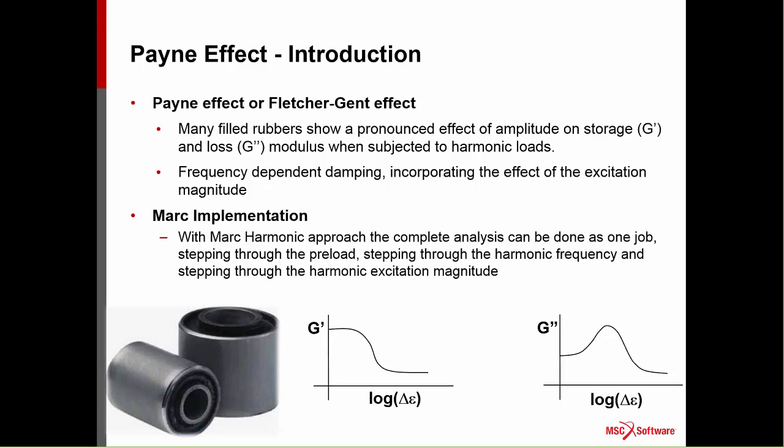So what this really does is it makes that harmonic simulation really a nonlinear harmonic simulation. So we basically apply some preload, we apply an excitation onto that preload. We basically take a look at the amplitude of the results, and then we use that amplitude of the results to tune the damping and run this again. So we're running really an iterative loop within the harmonic excitation.